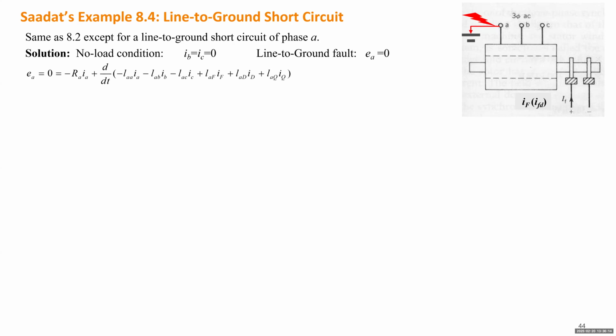Power transformation is useful especially for balanced conditions which are close to steady state, right? You can simplify. If the system is unbalanced but also not far from a steady state, there are not many differences between the equations in the ABC frame or the 0DQ frame.